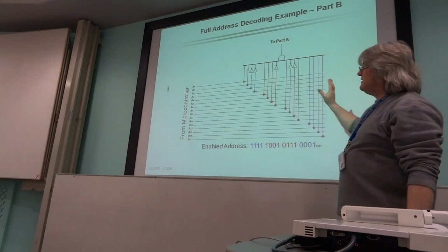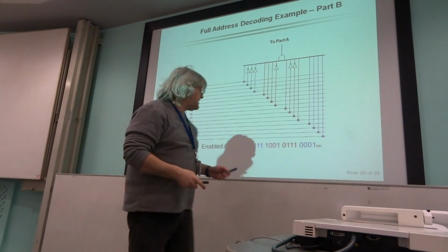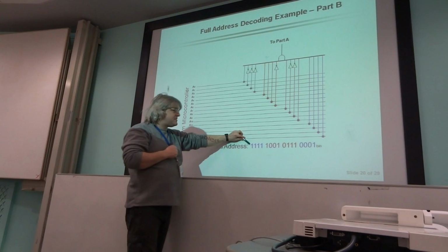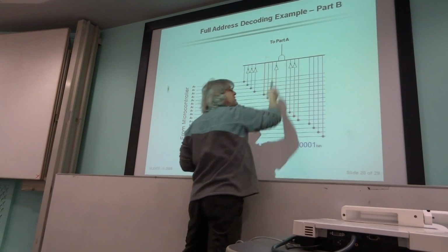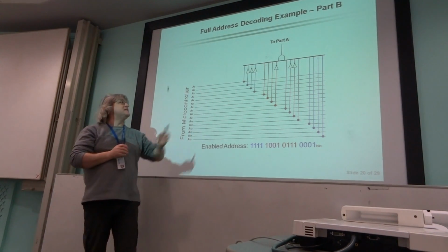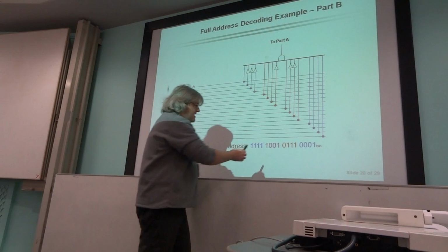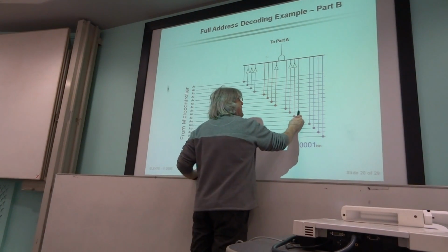This is a second combination that's feeding into that previous slide. And here's the second set of values that we must use to wake up this device. So high, high, high here. So there's those 4 feeding into those 4 inputs of the 16 input AND gate. This is a different AND gate to the one on the previous slide. Then we've got, where are we? High, low, low, high. So then the highs come in here.